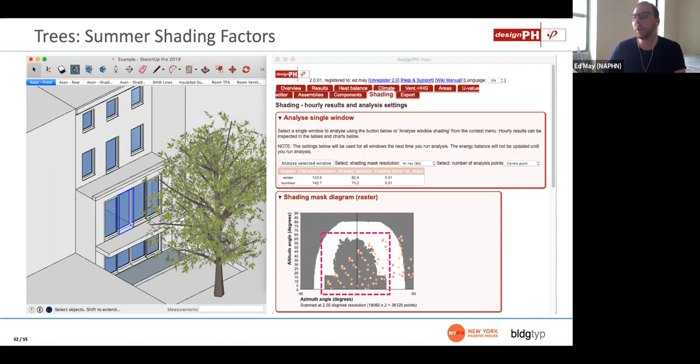Then building footprints and building floor levels we get from OpenStreetMap, a publicly accessible GIS database. It allows us to get building heights in most cases, in most municipalities, but if not heights, then at least the number of building levels. For sure we're able to get building footprints if you're working in an urban location. Most places are going to have it through OpenStreetMap at this point.